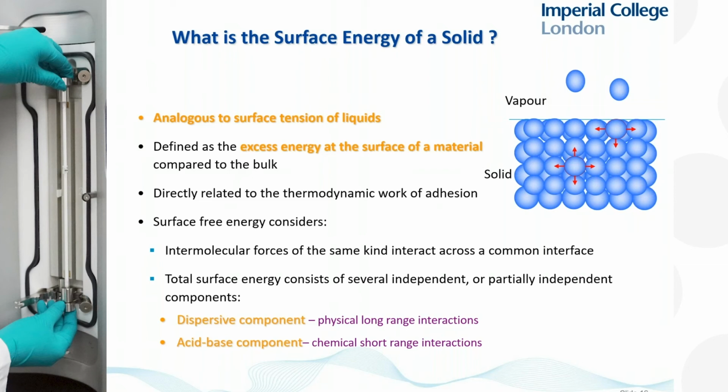All fluids, all solids will exhibit some van der Waals forces. These are long-range molecular forces. And we'll see some examples of those in a moment. And some materials, those that have polar groups or acid-base groups, such as OH or hydroxyl groups, will also exhibit, in addition, some acid-base forces or polar forces. And we'll see some examples of both of those in today's presentation. So when we measure the surface energy or any of the surface tension, we're actually probing the intermolecular forces of our liquid. In this case, we're looking at the intermolecular forces in our solid. And those forces are helpful to understand many different sorts of behavior of our particular materials.